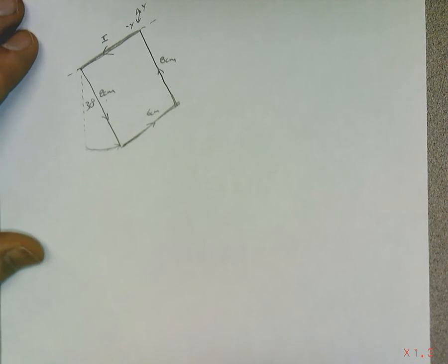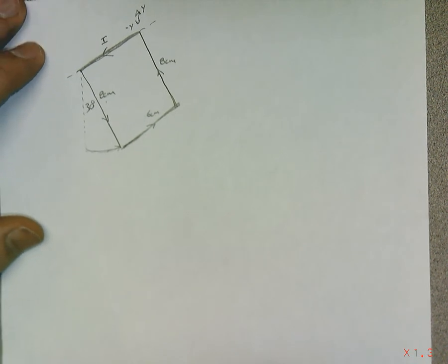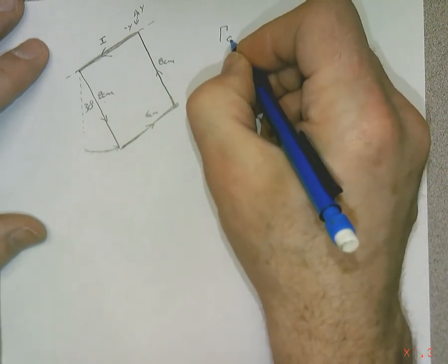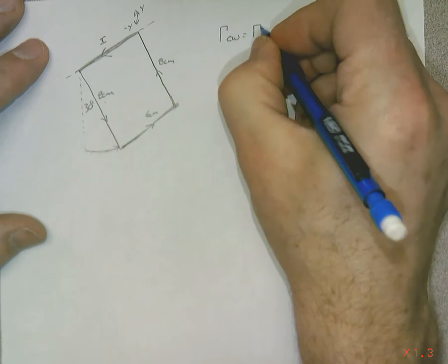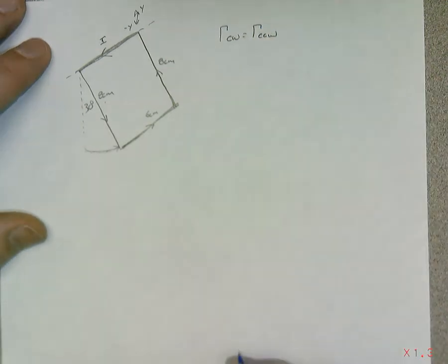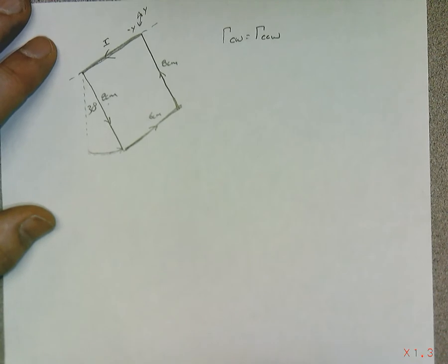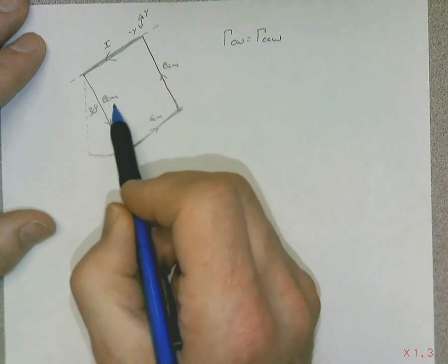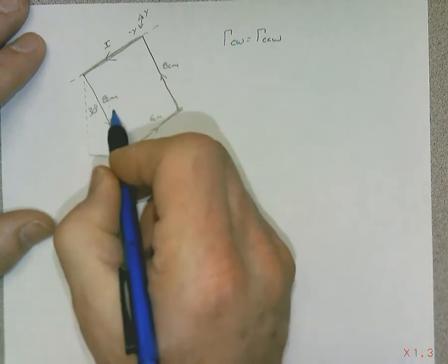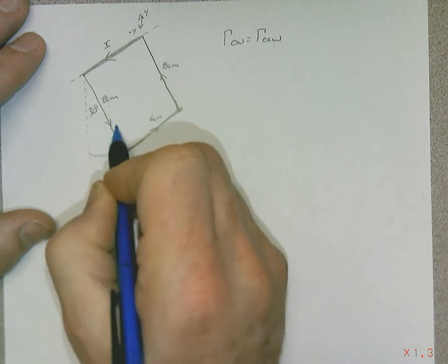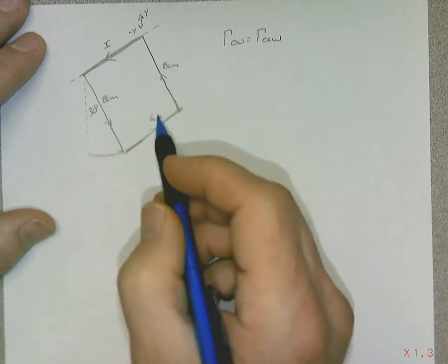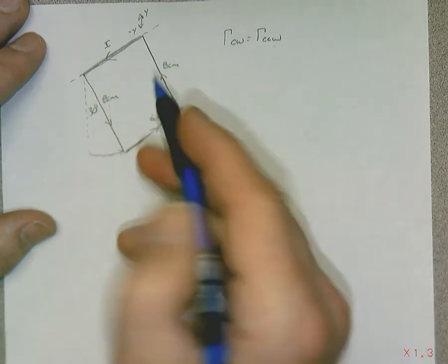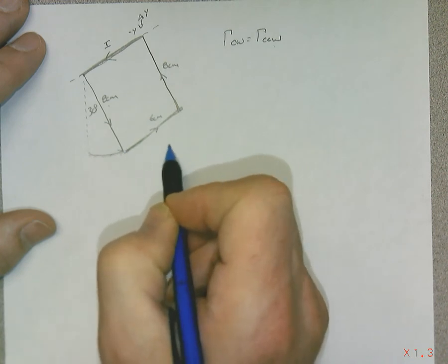essentially, what we're going to do is look at this in terms of torques. The way we're going to look at this is to say that the torque clockwise is equal to the torque counterclockwise. That should be fun, and that's familiar ground for all of us. So the clockwise torque, and again, that's not vector direction, is gravity trying to spin it down this way. And at the same time, the magnetic field, along with the interaction with current, is trying to rotate it the opposite way.